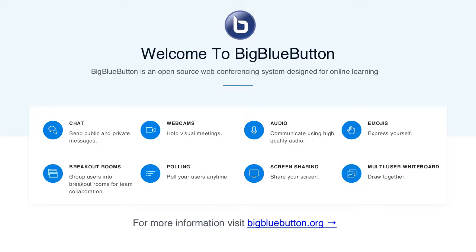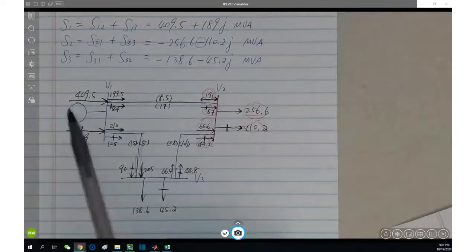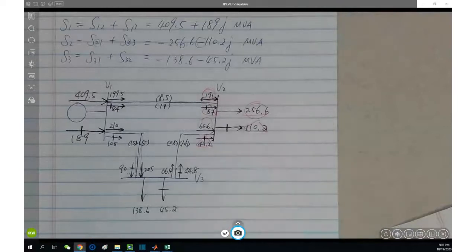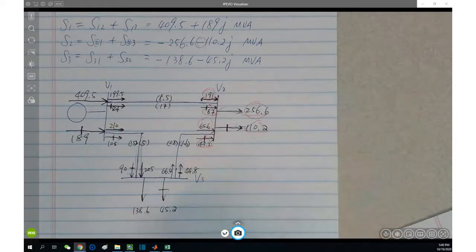Yeah. All right. What I'm saying is that how you do this is basically the load. This is the source. These two are load. Load might be capacitive or inductive. Of course, the resultant reactive power could be positive, could be negative. However, since this is a load, this should receive the active power. Right? It doesn't make any sense if you're providing any active power. As to reactive power, well, it's up to whether it is capacitive or inductive. That makes sense too.